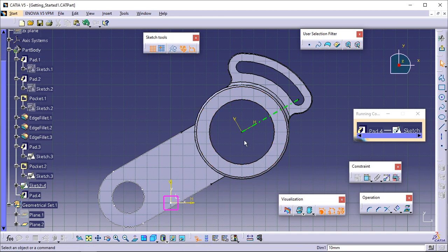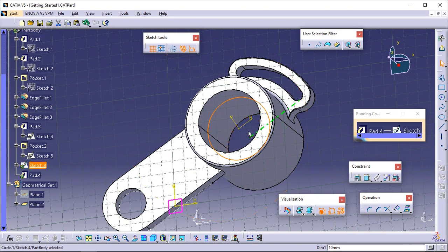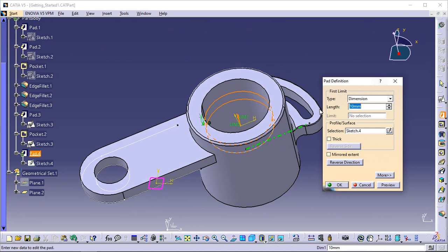Select the internal cylindrical surface of the part as shown. Select Project 3D Elements in the Operation toolbar. The projection is created. Select Exit Workbench from the Workbench toolbar. You are now back in the Part Design workbench. Both the part and the dialog box are still displayed.